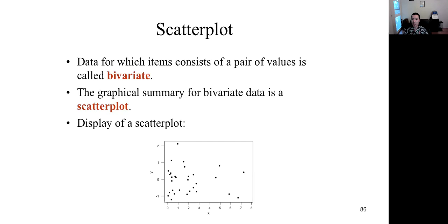So we do research on concrete materials, and we always plot scatter plots because we try to find correlation between certain parameters. For example, how the strength of the concrete is affected by certain values, such as the temperature or water to cement ratio. So we try to find a correlation between the strength and these parameters using a scatter plot.